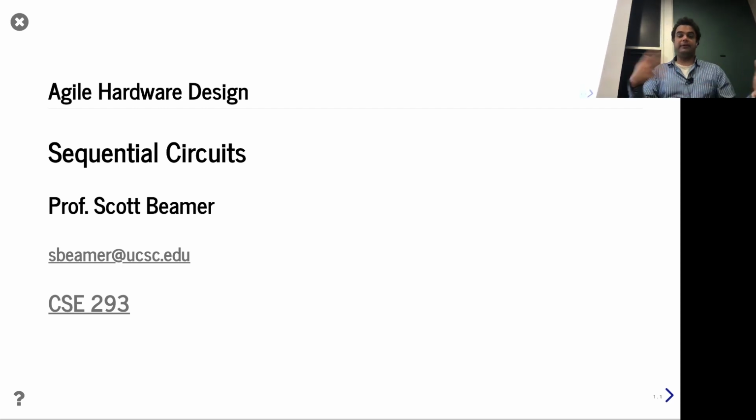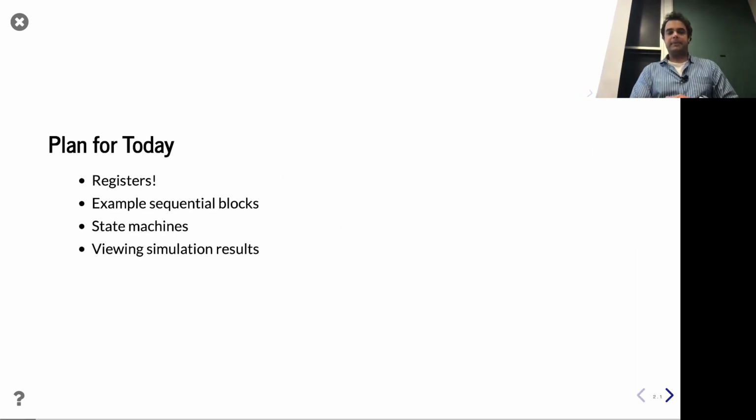And so today we're going to have a lot of fun showing how to incorporate registers into our designs. Later on, we'll talk about memories as a large collection of state, but for now it's just a single register or two at a time. We'll also talk about waveforms and other things that might help with debugging and getting more comfortable with the language. So as said, today we're working on registers, talking about sequential blocks, and of course putting the two of them together to make state machines.